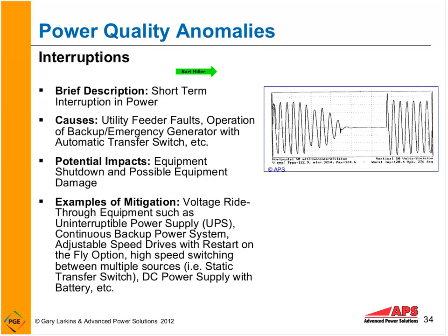And generally, we're going to see equipment shut down, but there are some technologies, depending on what we're looking at, to either back up the control systems, or, for example, an adjustable speed drive could be used here. We used that at one facility. We put an adjustable speed drive in that could restart the motor, sync back up to the motor with the control systems being backed up. And so when there was an interruption, they did not lose their process, where with a standard motor, they lost their process every time. So I've given you some examples of different mitigation equipment, some things that we may look at here to help protect or to provide ride-through from interruptions.